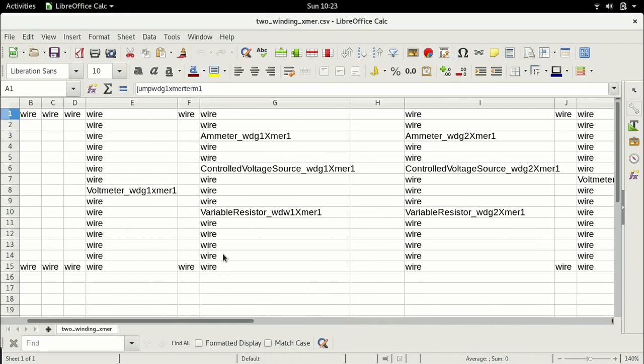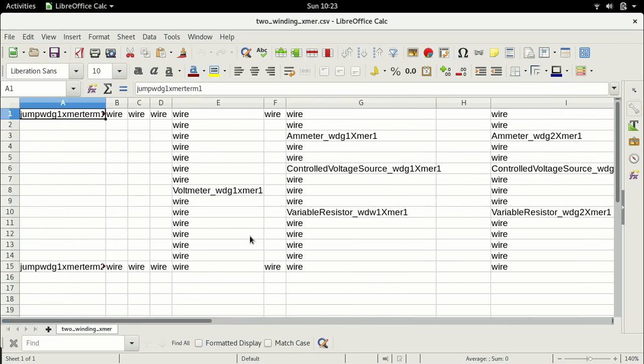That change will be in the polarity, right? If you look at a flyback transformer, you will notice that the dot polarity of the primary and the secondary are the opposite. So in a flyback transformer, the primary winding will have a dot on the lower terminal, and the secondary will have a dot on the upper terminal. This is typically how it is because the flyback is that kind of transformer, but we won't start it right away. We'll go to that gradually.